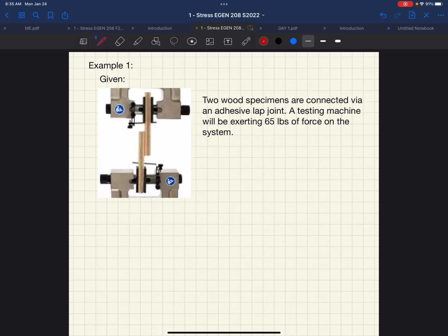Well, we'll deal with why those need to be glued together later on in the class. But a lot of times they do testing of those joints to make sure that as they glue and lap each of those 2x4s on top of each other, they have enough strength in order to get the composite behavior that somebody wants. When we lay those 2x4s out and stack them up, it makes the beam stronger, it makes it taller, increases our moment of inertia, areas, a lot of the material properties. And so what they'll do is take two pieces of wood, 2-dimensional pieces of lumber that they would plan on gluing together. They would create a joint in which they would know the cross-sectional area.